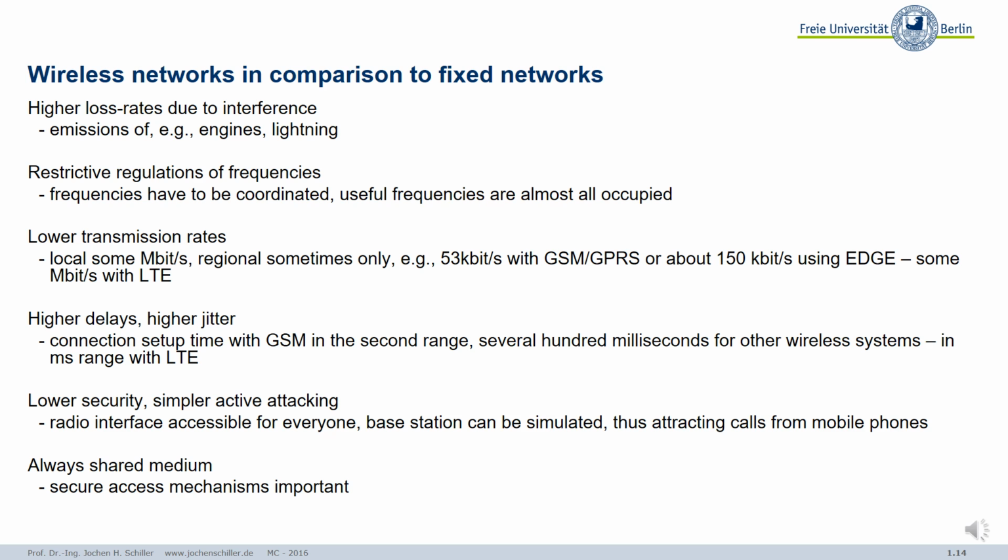Why? Well, the problem is, depending on your connection quality, you have to put a lot of effort into forward error correction because of the high bit error rates. And forward error correction means you have to do some computation with your data.